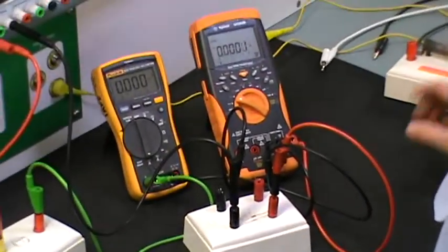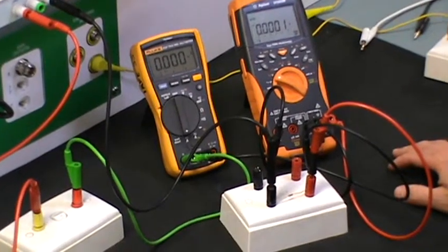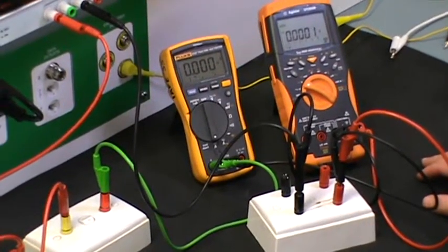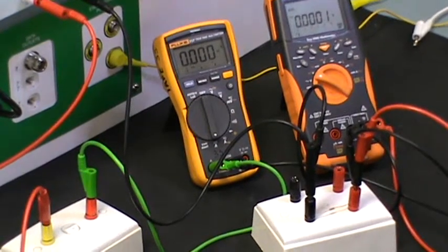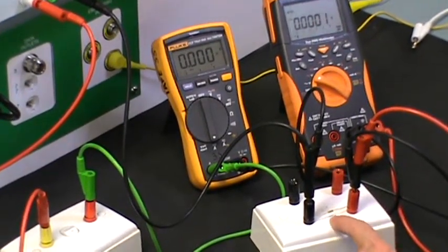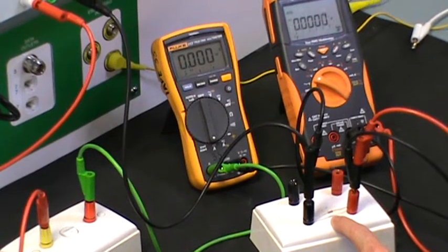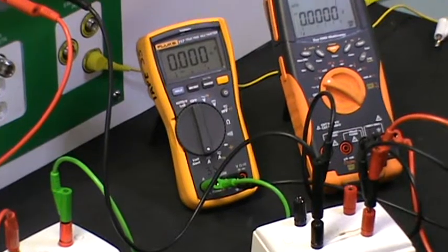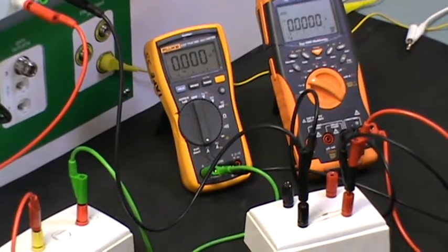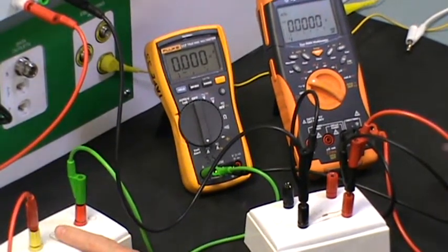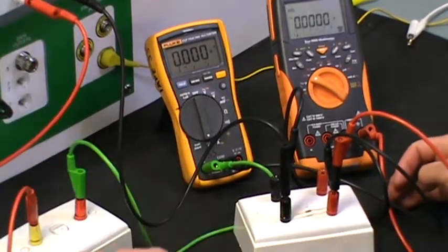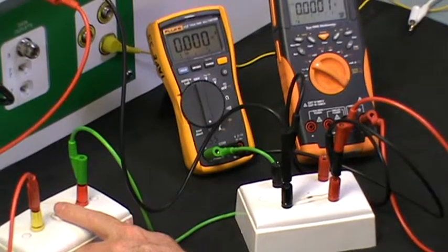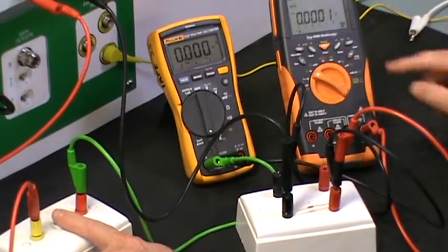What is going to happen when I turn this power supply on? What is going to happen to this half watt resistor? Obviously the temperature will increase, we know that, so we've done that. I suspect we're going to have some serious issues with this resistor, being it's rated at half a watt and we're about to expend 10 watts through it. So quite a bit of power is about to flow through the resistor. Let's have a look, let's see if we can screen grab this. So I'll turn the power supply on first, so it's 10 volts, and I'll flick it on and see if you can see the resistor, the current and the voltage.